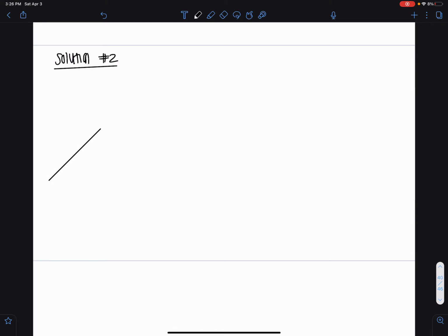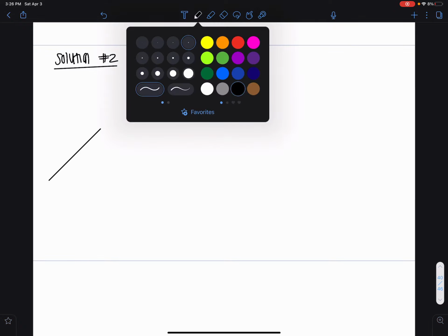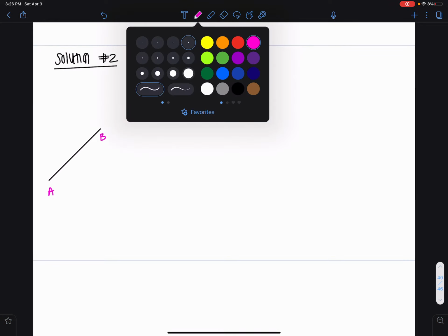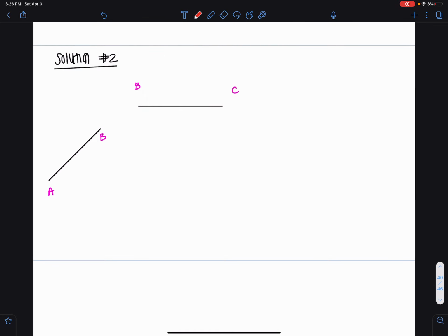So I'm going to draw the FBD of the whole system one more time. Okay, so here we have point A, point B, and point C. I like to call this exploding the system so we can expose all of the forces. That's why I'm not connecting point B. I want to explode it so I can see what's going on here. So here at A, I have the pin, Ax, Ay.